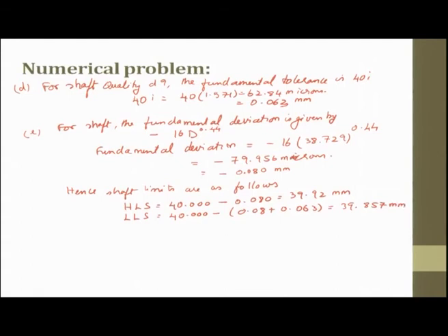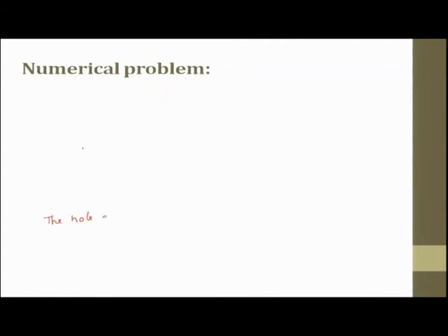Now, the shaft tolerance is going to be 39.92 minus 39.857 millimeter, which is approximately 0.063 millimeter.